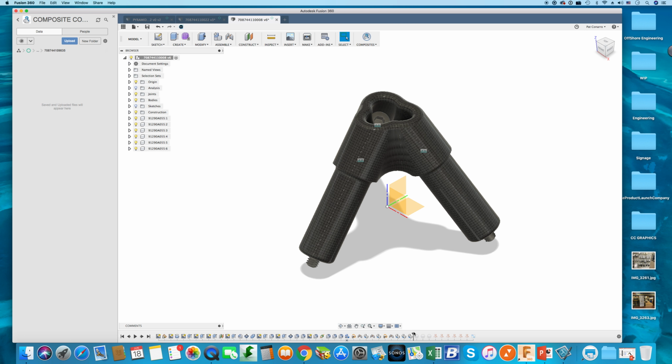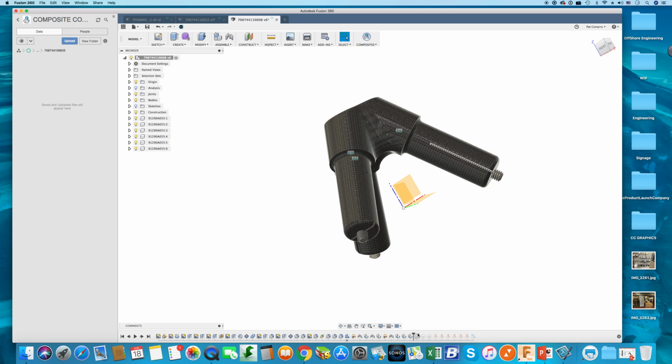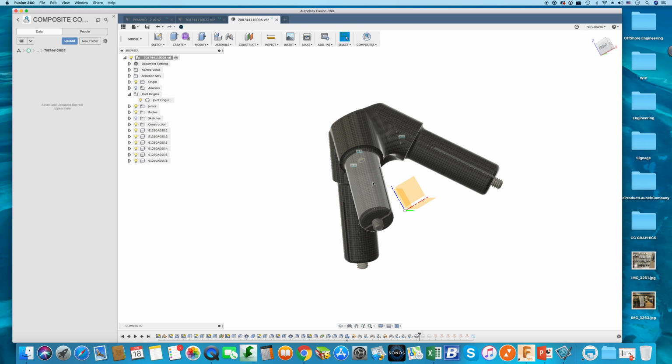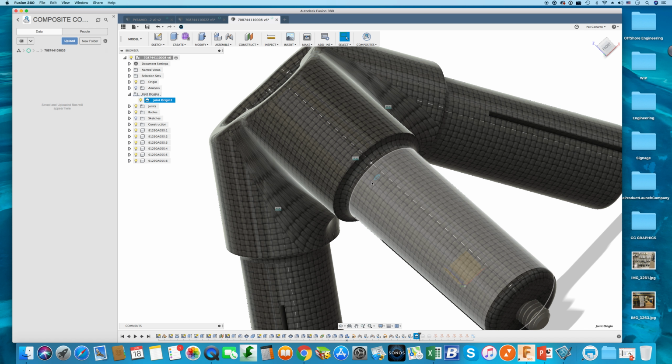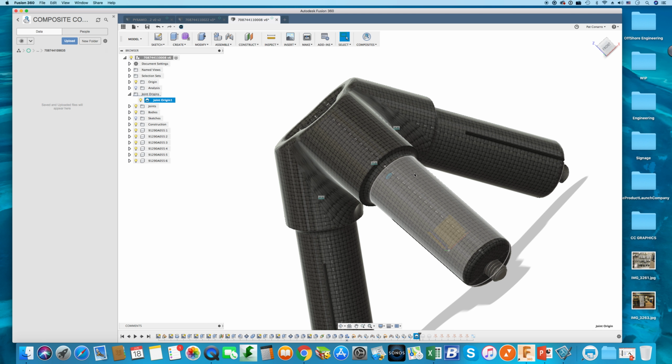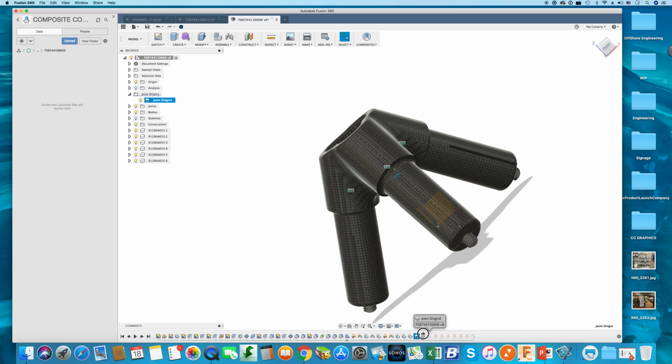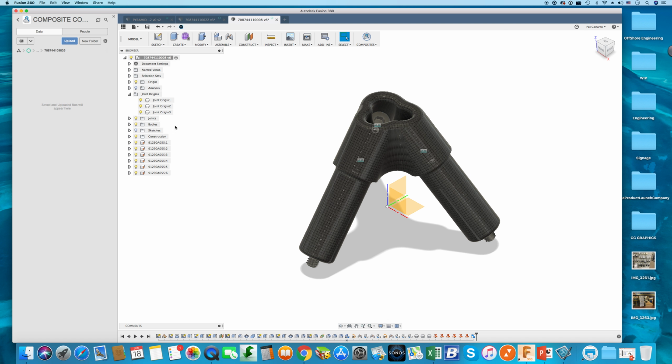And then what I do is I put these joints here. So this is a joint where the tubing will mate right here. I click on that, and I put it in the center of the edge where the tube butts up against this. So it's real easy for me to mate tubes on here and all that. So you'll have to learn about that in Fusion. And so now I've got the part done, and I ground everything.